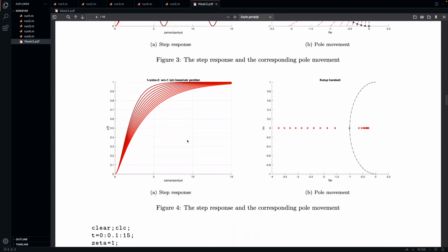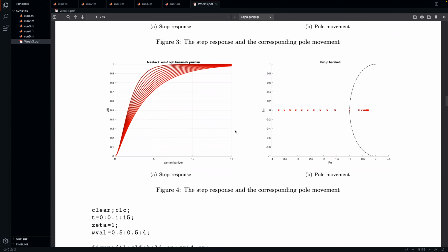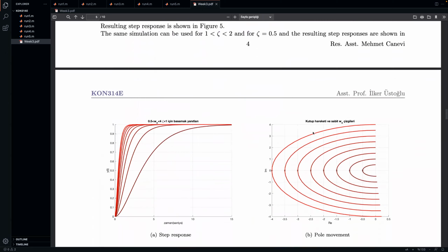Those systems are not really the ones that we look at, because even the omega n radius loses its meaning: one of the poles tends to the origin, the other is tending to the left on the S domain, and we have this weird combination of fast and slow poles, which messes up the whole idea here, and it doesn't have overshoot. So why would we use it? We could maybe go with the critically damped, and that's the best we can do here.